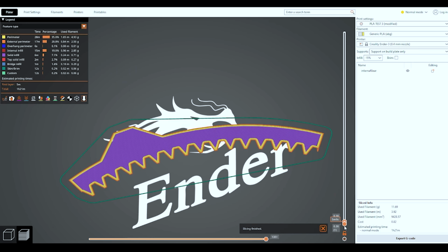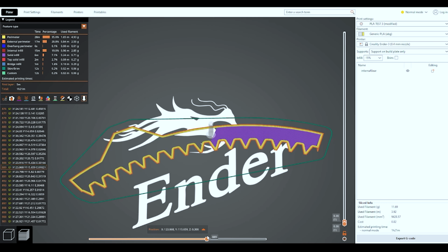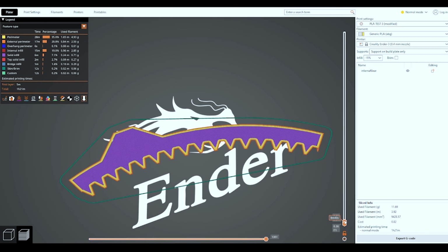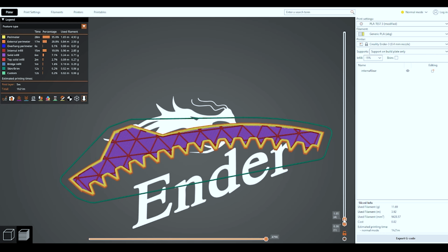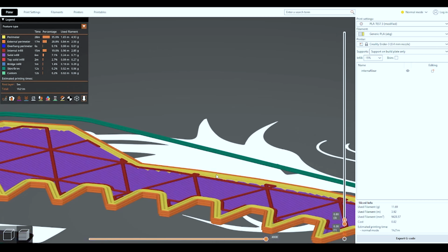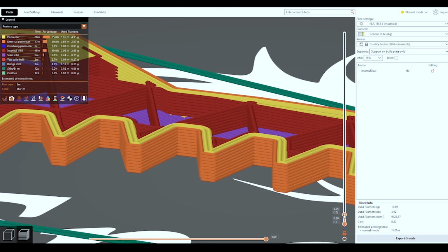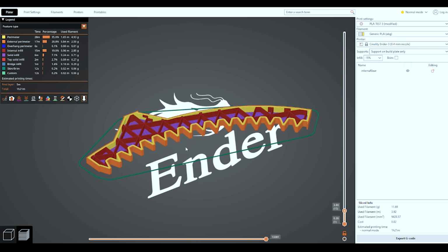This is the first ever layer that's going to be printed. There's nothing on the plate. We make the first layer, then we go to the second layer, which is also full. But the first 2 are full, then we start making the infill. And that parameter is really important.